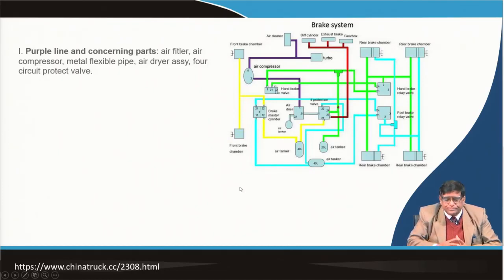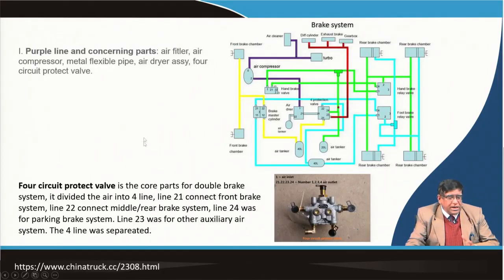You can see also how in your dump truck the different brake systems are there. You can have the air compressors, you have got the front brake chambers here, and you have got the rear brake chambers here. With these 4, we can have 3 axle vehicles. Depending on this, the circuit will be changing. You can see here we have got different types of lines, colors shown depending on the function. So, this type of diagrams and circuits are there in all machinery.